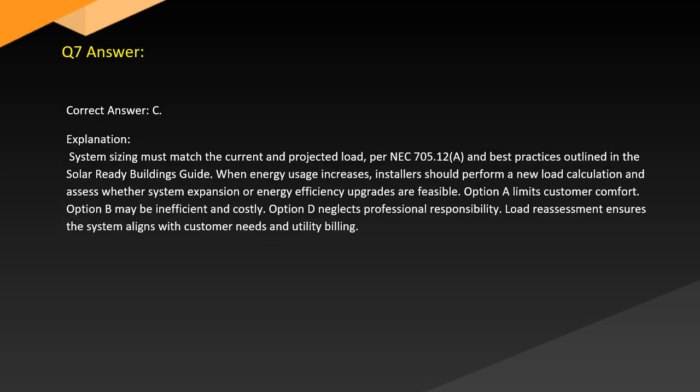Answer. Correct answer: C. Explanation. System sizing must match the current and projected load per NEC 705.12(A) and best practices outlined in the Solar Ready Buildings Guide. When energy usage increases, installers should perform a new load calculation and assess whether system expansion or energy efficiency upgrades are feasible.